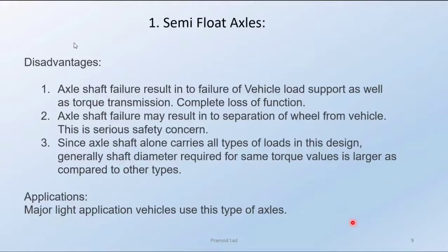As the axle shaft alone is performing all the necessary duties, that is taking the vehicle load, transmitting the torque and taking the side thrust at the same time, if the axle shaft fails, all the functions come to an end and a complete loss of function is observed in this case.